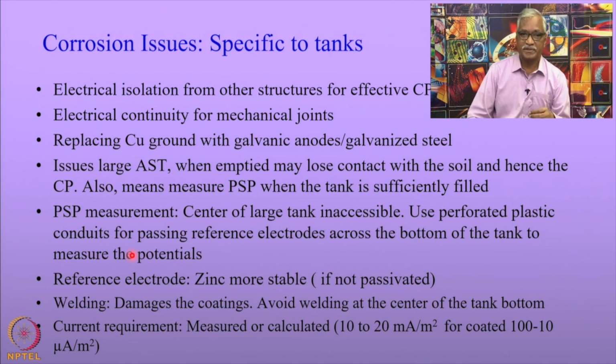So, zinc electrodes can be used, because they are buried in the soil. The only condition is that zinc should not be passivated. The zinc sometimes gets passivated if you have carbonates in the soil.